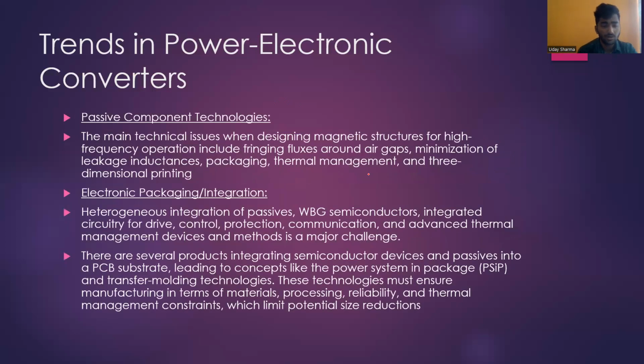And a few more trends in power electronics are passive component technologies. The main technical issues in designing magnetic structures for high frequency operations include fringing fluxes around air gaps, minimization of leakage inductance, packing, and thermal management, along with three-dimensional printing. These passive component technologies revolve around this three-dimensional printing. Let us see it as a part of electronic packaging and integration.